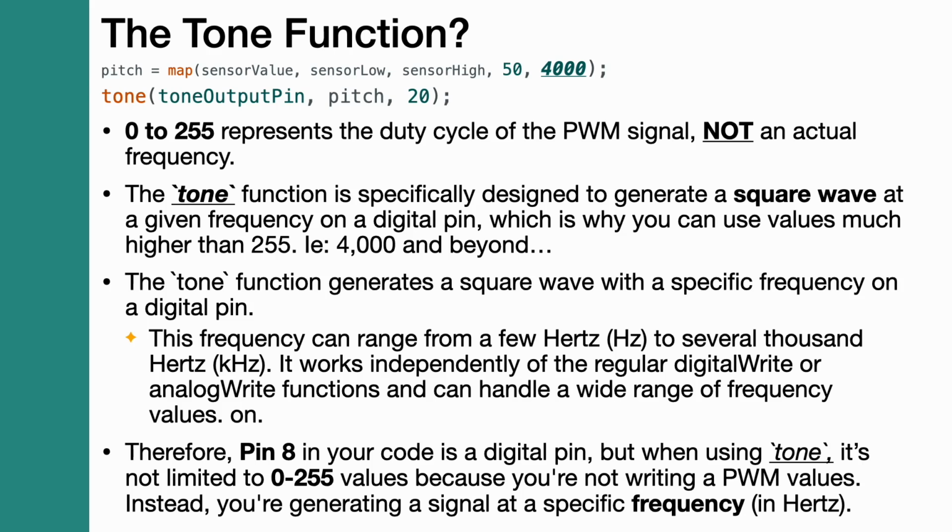And so to clarify some of this, 0 to 255 is the minimum and maximum value. How frequently you give that value to the pin depends on what hertz the chip runs on the given board. So at 4,000 hertz, even if I give it the value of 255, which the pin can handle, I'm just going to give it 255 4,000 times a second.